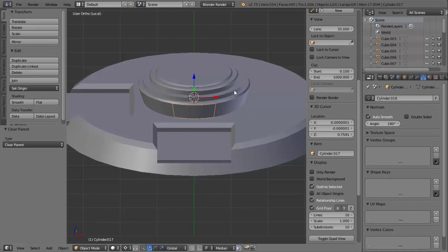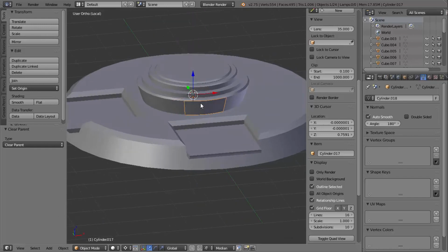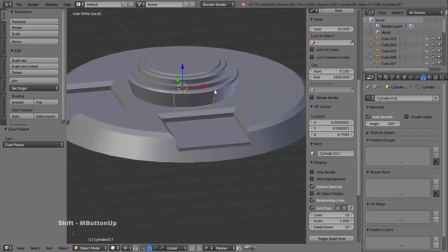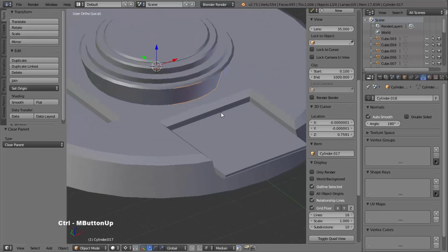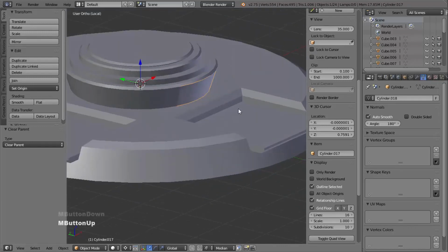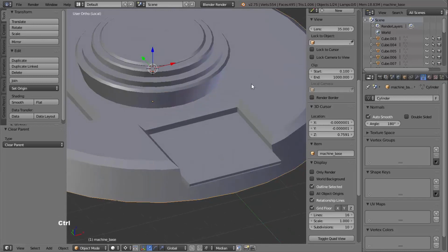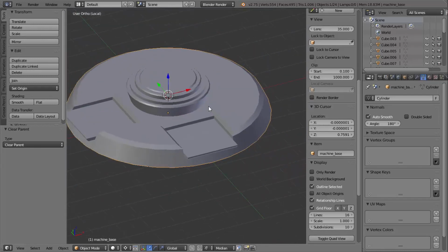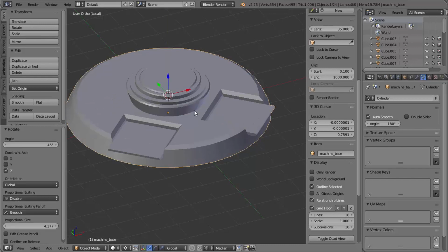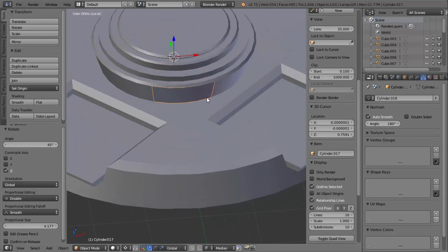And the reason I've done that is because I temporarily want to rotate this base object 45 degrees, so that when I start extruding the foot geometry out of this object here, I'm not going to be protruding and sort of hanging over the top of this indentation. So I'm going to select my base object and then rotate it 45 degrees, so R, Z, 45. So now when I select it again, I can extrude out and it'll be resting on this bit of floor.